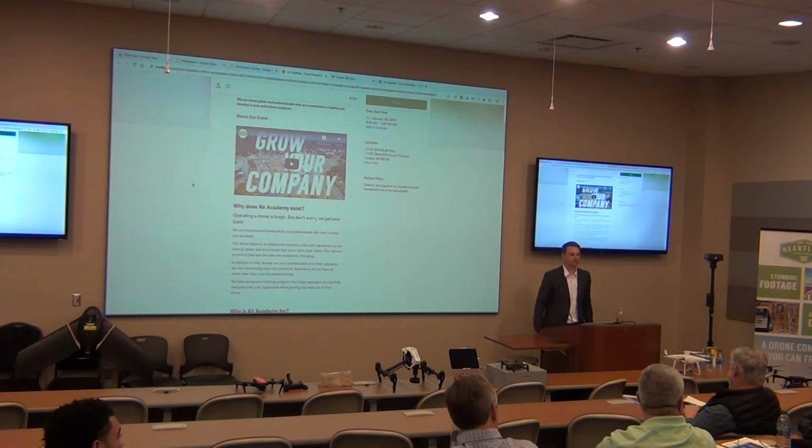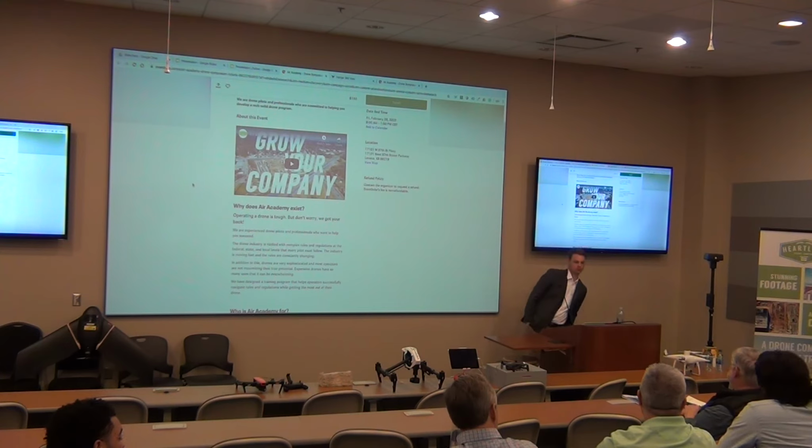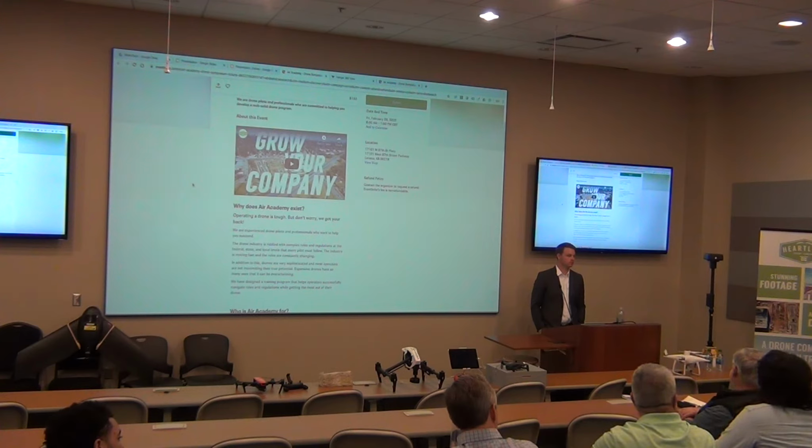Okay, so the drone can give you a precise map that you can do an overlay with. And now the ground's been partially graded. Right, so nothing's any good anymore. And you can help with that. Sure, you'd be able to see your contour lines, and that would be an overlay. Then you would simply turn your plans into a PDF and overlay that, and wherever you touch on the computer screen, you're going to get a constant readout of X, Y, and Z. Then all you do is go out in the field with a rover and go to that exact location.